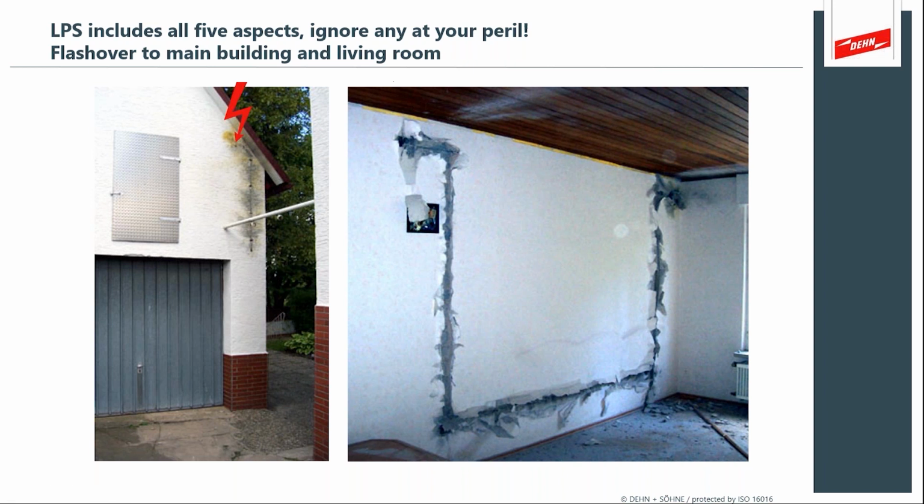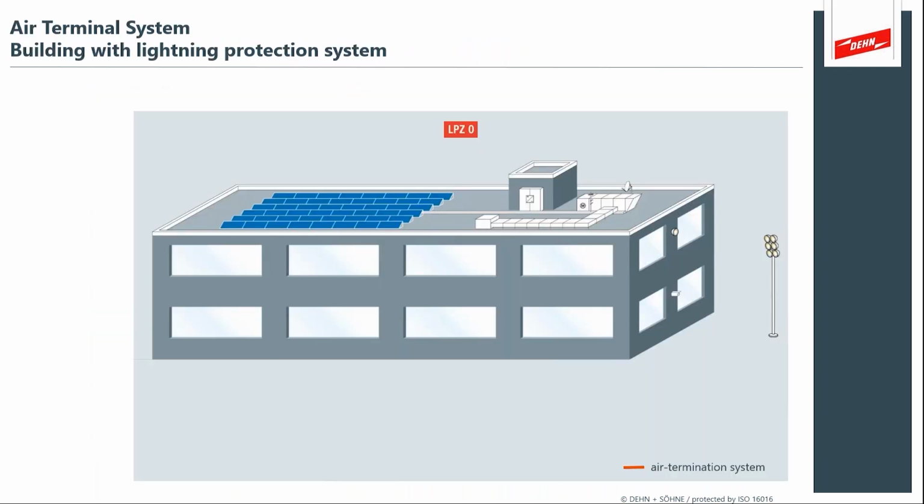And so whenever we're discussing an aspect of lightning protection, say the placement of air terminals, you always need to pay attention to all of the factors. You need to look at your down conductor and your earthing, but you have to always pay attention to the separation distance and to the bonding of metal structures. And this shows up in both IEC and NFPA standards for bonding distance and separation distance, which essentially are very similar or the same thing. And this is a nice illustration of what that looks like.